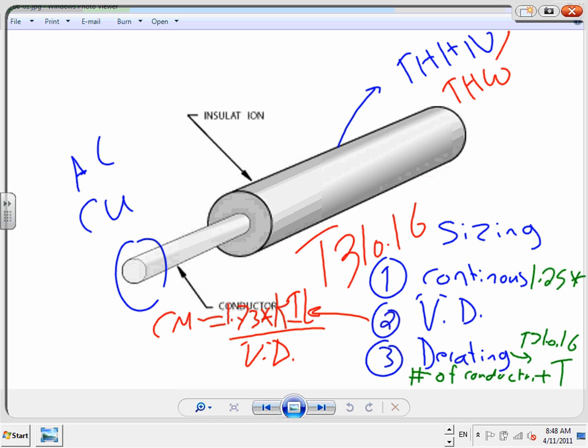Voltage drop, always assume, when we do voltage drop sizing, guys, that it's 3% voltage drop. So, Brad, if your system is 480, multiply it by 0.03 and put the number over here. So that's my voltage drop. 1.73, anybody can tell me why 1.73, guys? That's three-phase, thank you. And I always emphasize three-phase because we're commercial now. Everything that we do is three-phase. K is a constant given, guys, at 12.5 or 18. This is always given. I is the current, and L is the length in one direction.